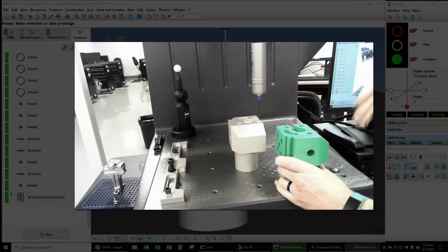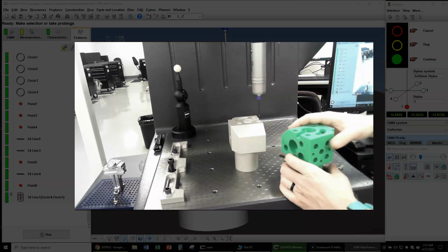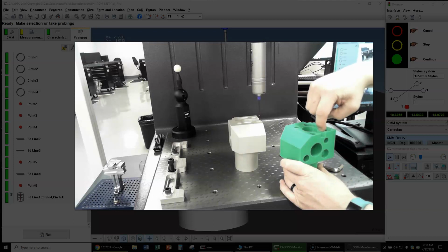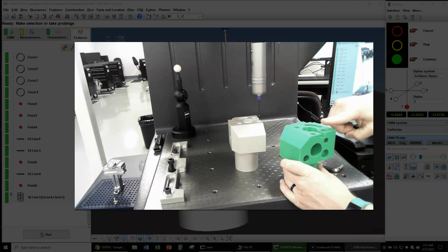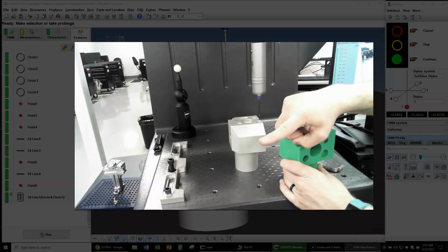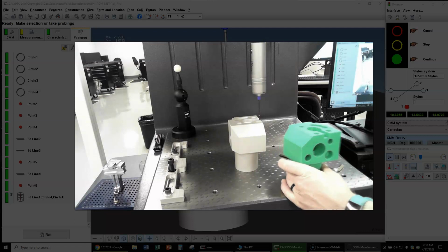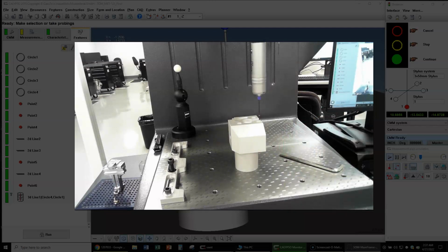And it actually gets added to a lot of other things. So in this case, the clearance distance, if applied to this slot, would first, if we touch that as a line, the normal vector or the normal retract of the line would be that way. It would add the clearance distance plus the retract, and then it would go to our clearance plane. So clearance distance isn't what it really sounds like, and it almost never applies unless you have inclined features. Always wants to be 0 unless you have an inclined feature. So I think there may have been a video where I got that twisted and misspoke, but what I just said here is 100% sure.